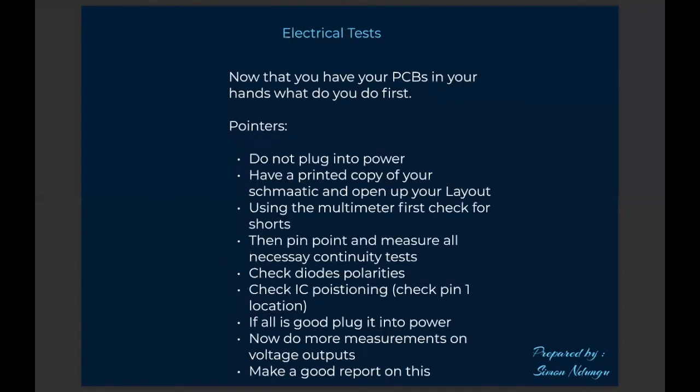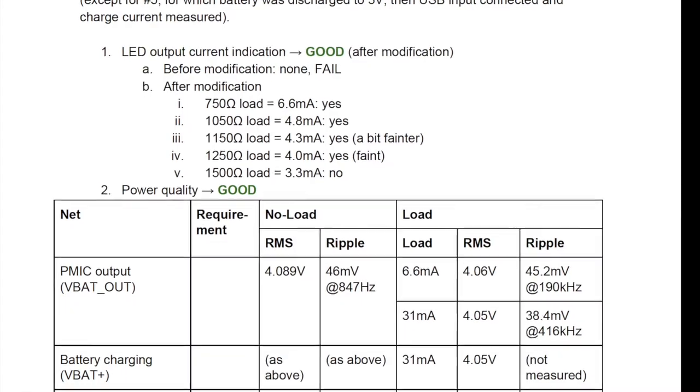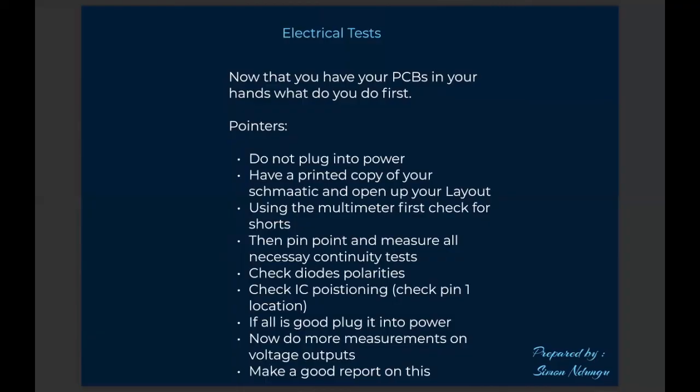Once you get your PCBs, you start doing some engineering work again. This is where you perform some electrical tests. You have your multimeter. You are checking the voltage and the continuity. Is this resistance okay? Here you are checking the polarities of the diodes. Have they been positioned in the right orientation? Stuff like that. Just have your schematic, check through, and ensure that this is the voltage that I was expecting. I have this test point, is it what's coming out here? This was supposed to be connected here. Have the tracks been done very well?